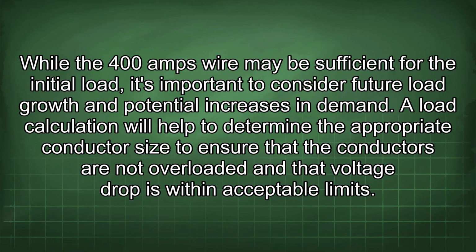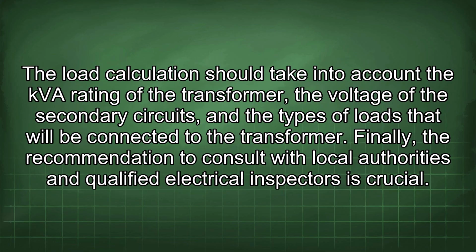A load calculation will help to determine the appropriate conductor size to ensure that the conductors are not overloaded and that voltage drop is within acceptable limits. The load calculation should take into account the kVA rating of the transformer, the voltage of the secondary circuits, and the types of loads that will be connected to the transformer.